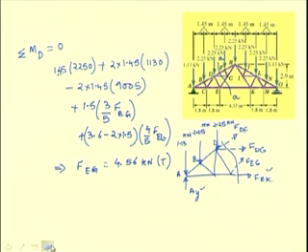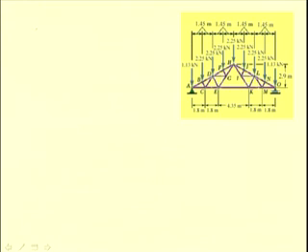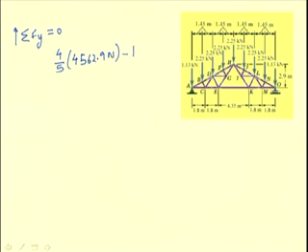Now, we can use the force summation equation to determine the other two forces. First, we use the force summation about y axis. The various direction cosines are available. This is for the member EG. The direction cosine is 4 by 5 times the force in this member, minus 1 by root 5 for the force in DF for this member.